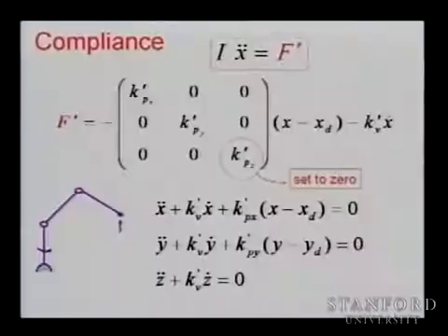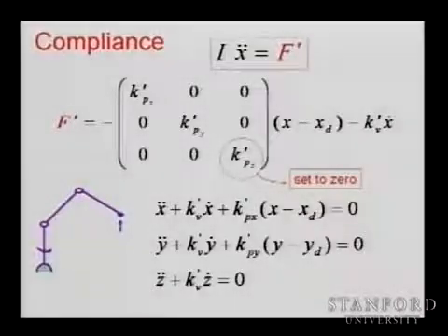So when it feels there is any force, it moves away, which means we need feedback. We need a force sensor. And this is really the requirement in order to interact with the environment. Most of the time, actually, you want to apply a specific force on the environment, and that requires control of forces. Here we have only removed the position control from 1 degree of freedom, one direction.